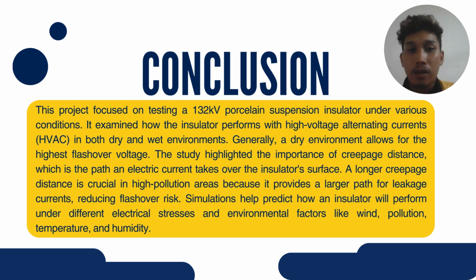Okay, so we go to the conclusion for our project. This project focused on testing a 132 kilovolt porcelain suspension insulator under various conditions. It examined how the insulator performs with high voltage alternating current, which is HVAC, in both dry and wet environments. Generally, a dry environment allows the higher flashover voltage. The study highlighted the importance of creepage distance, which is the path an electric current takes over the insulator surface.